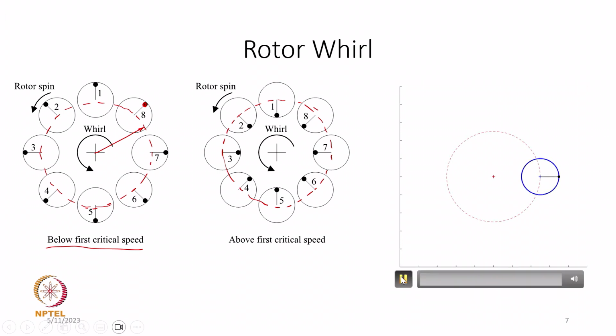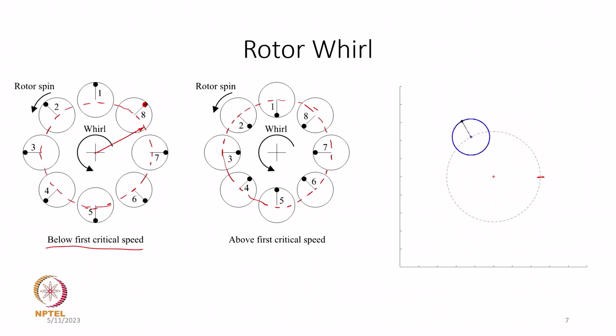Maybe I can show you this animation of how that motion is going to be. So, as it moves from this point, to start with, and then comes back to this point, you must notice that this shaft has spun by one full rotation, so 360 degrees. So, 360 degrees of this whirl motion, and the same 360 degrees of its own spin motion, will simultaneously happen.